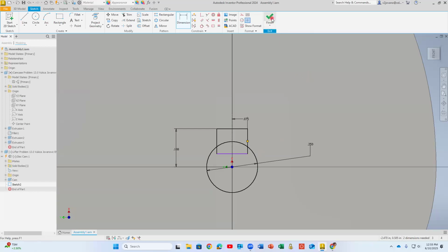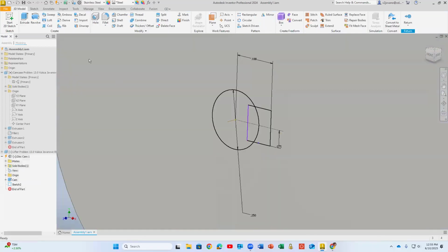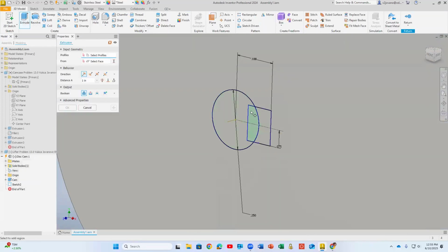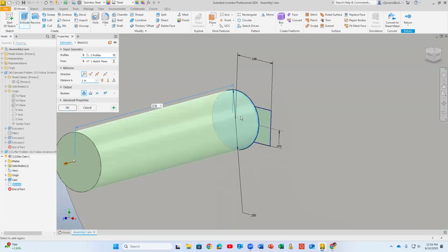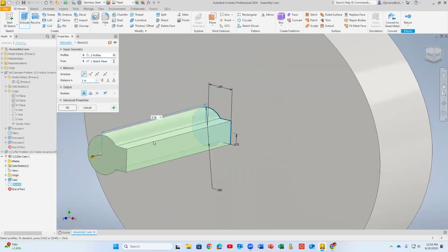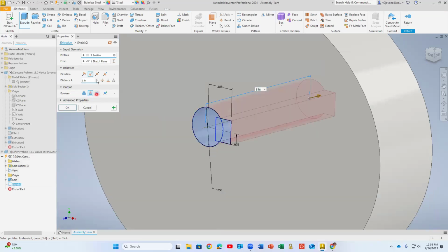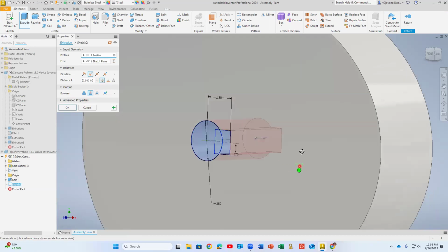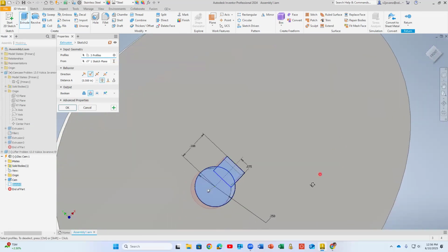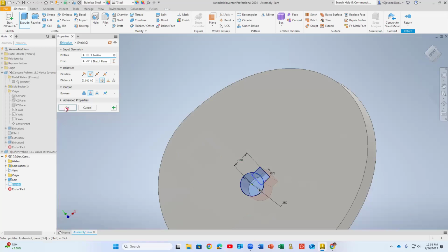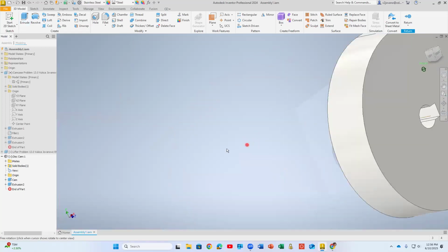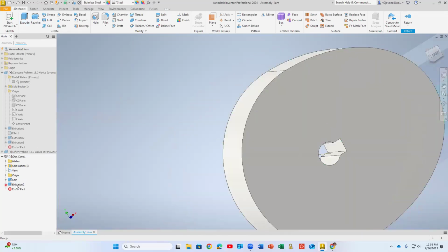Let me show you. I mean, easiest would be to cut, but I can even extrude with this. So look, I can show you that. So if I do extrude, you just have to select three times, you see. But you can extrude without even finishing trimming. And then I will switch this to cut through all, and basically I will have that cut. So you see, in the same way I have all the dimensions that I was looking for, but the cut is there.